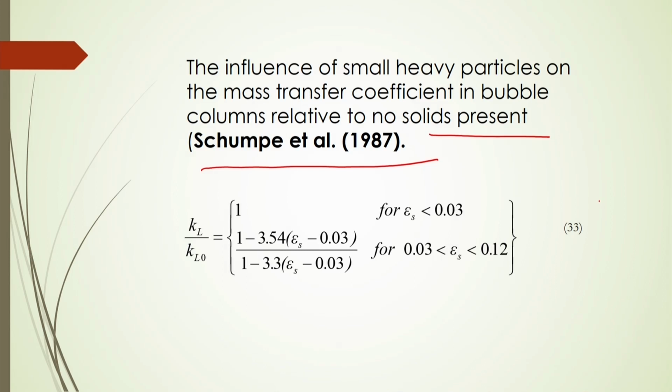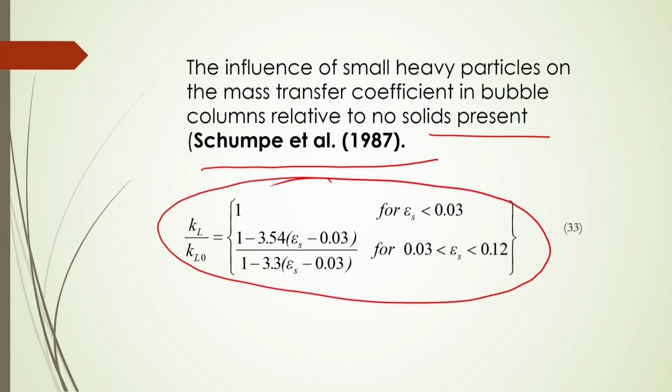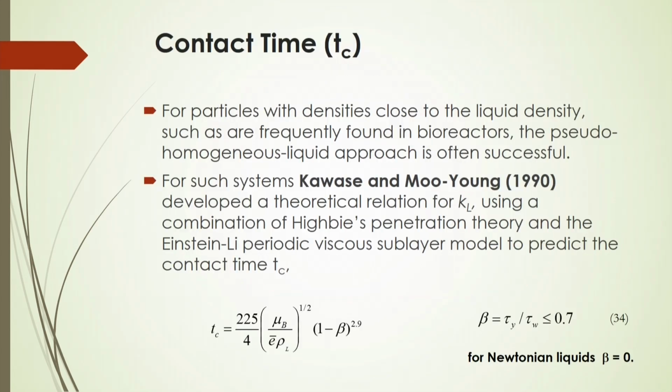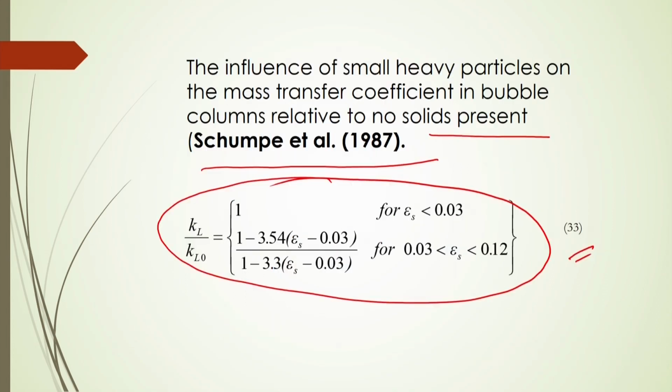1987, they have given these empirical correlations to calculate the mass transfer coefficients without solids. So, based on this equation, you will be able to calculate the individual mass transfer coefficients in the presence of solids, if you know the solid fraction inside the bed.